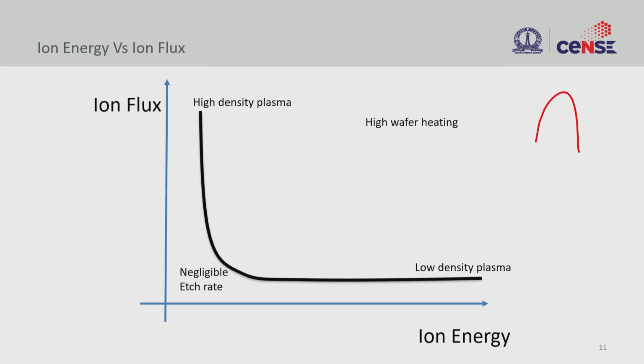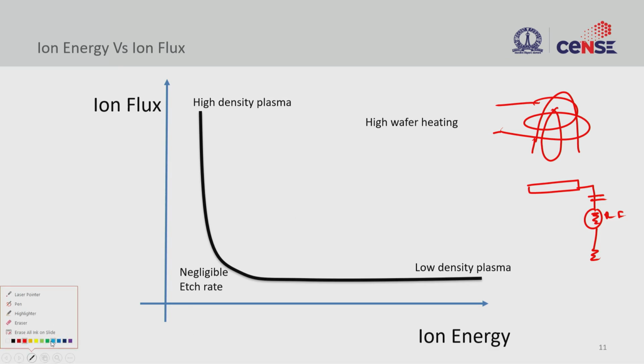So there is a dome, and this dome creates the plasma, and then my wafer is kept below this dome, and then here you put an RF, going through, of course, a blocking capacitor, and here you will also have an RF current feed. So when you generate it, plasma is generated here. You create plasma here.